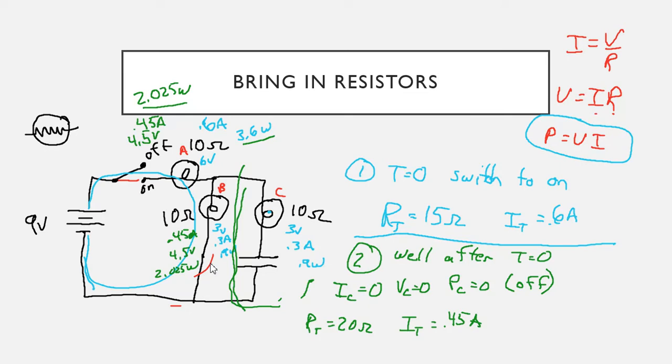And when this capacitor is fully charged, both light bulbs will now be the same brightness. A got dimmer, slightly, but definitely dimmer, and B got brighter, right? So by watching the light bulbs, we would know what's going on with the capacitor. And I know C is out, so when the capacitor is fully charged, light bulb C is out, and the capacitor is not doing anything.